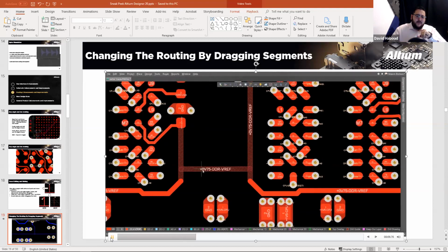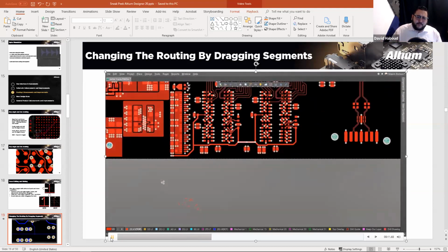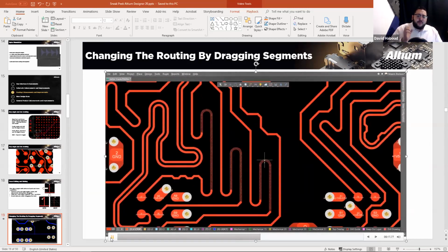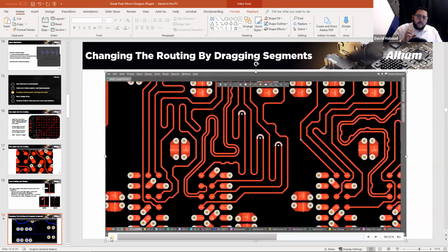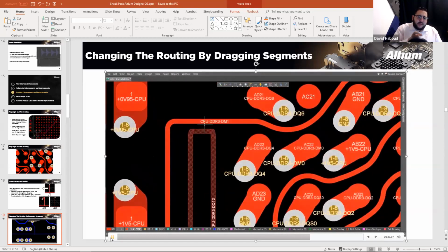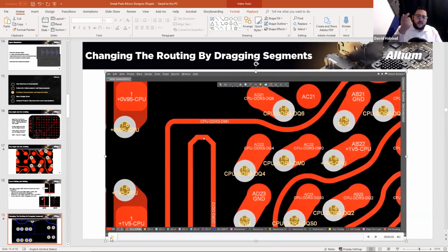And when you have the T-junction on either side, you saw that it moved both of them simultaneously. And you have these arcs here. Not only can you move the arcs, you can also change what type of routing is applied to them and gloss the affected area above it. So you saw here, it also glossed the trace above it.